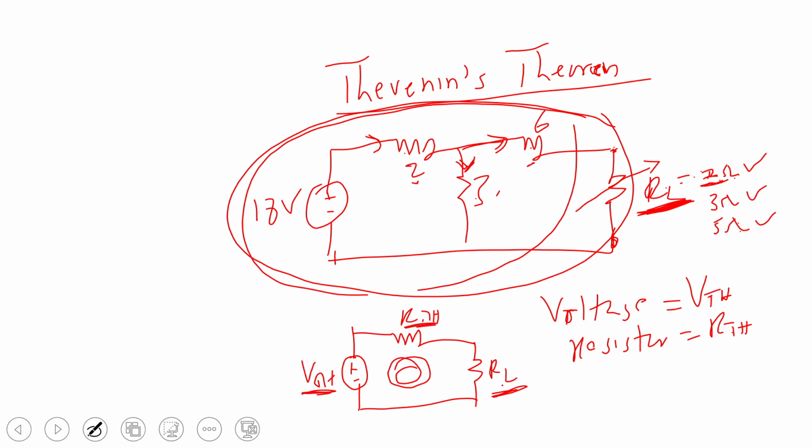Then the bulb that you remove, you come and put it in series here. And anytime this load resistor changes, you will not need to analyze the entire circuit here again. Just analyze this simple circuit and find the current in the load resistor. So basically that is Thevenin.